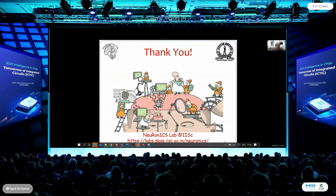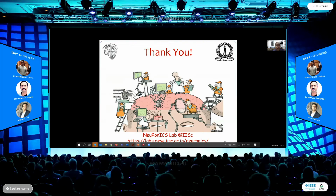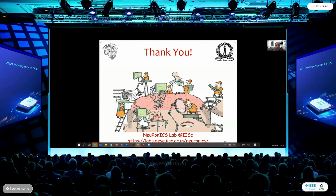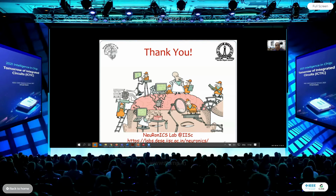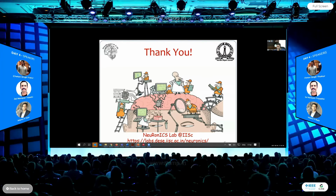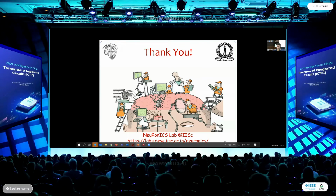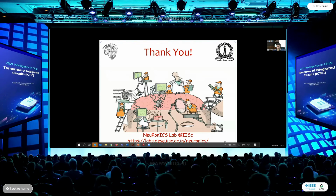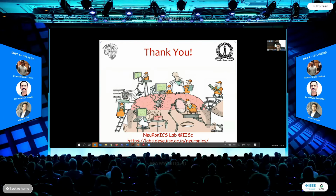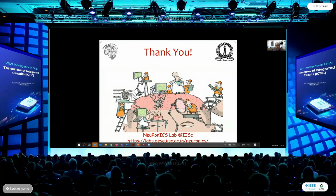Right now, some of the implementations were shown on FPGA. Do you think it would make sense to go further into ASICs or mixed-signal chips? See, right now, first we just want to demonstrate the feasibility. I would not recommend going for ASIC unless there is a real application where you really want to see the power, performance, and area metrics. The idea is just, can you show some prototype and say, yeah, it works.